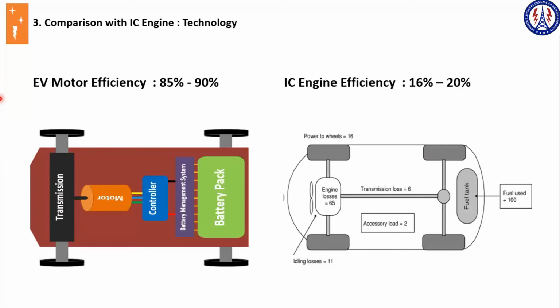Caloric value is measured in kilojoules per kilogram, like 1 kilogram of fuel burning, how much energy it is producing, right? Let's say 1 kilogram of fuel we burn here is producing 100 kilojoules. After that, 100 kilojoules reaches here and only 20 kilojoules is converted into motion, which is running the vehicle, and 80 would be lost in the form of heat, friction and all.